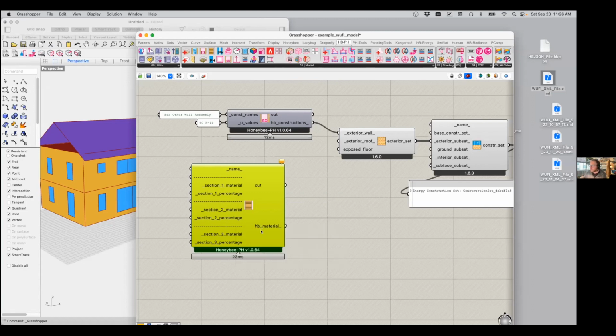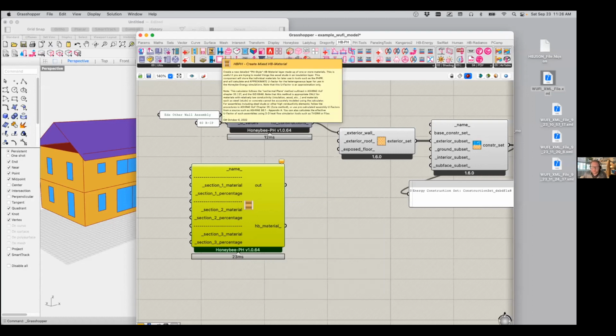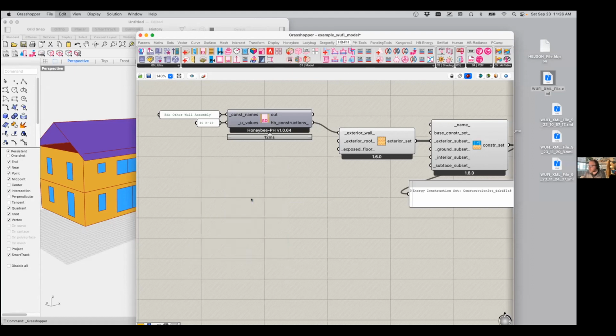This becomes a material layer, which can then become part of the total assembly there. So there's this little sort of stud element there. So you can do studs. That only works for wood studs. You would not be allowed to do steel studs using that method, but that's an ISO rule, right? So you're not allowed to mix steel studs into your assembly layer there. But you can certainly use it for wood studs if you wanted to.